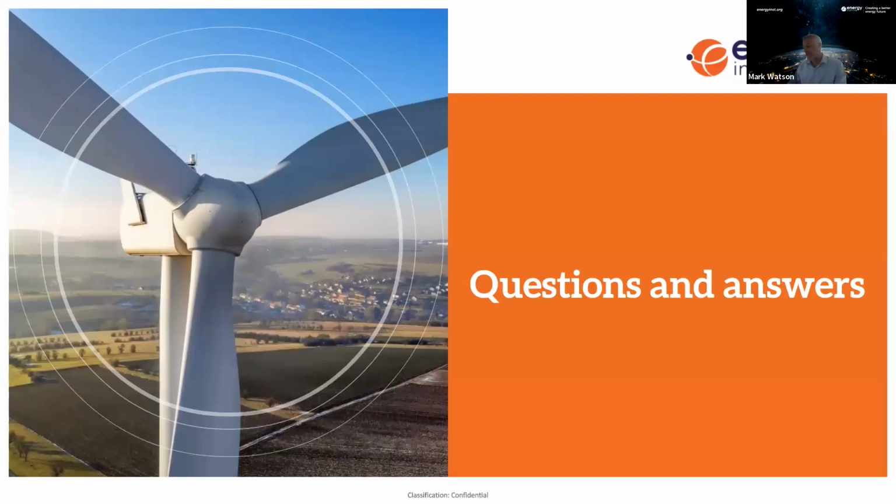You don't need wind turbine safety rules training or knowledge or competence to be able to put your signature in that box. It's very similar to if you were an SAP or an AP working on another boundary discussion, and somebody might issue you an isolation and earthing certificate, in which case you would be asked to sign to say that your isolations are in place, but it could be a different company's document.